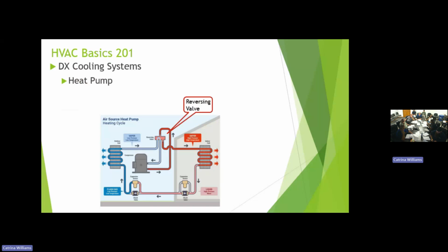So now you get that reversing valve for the heat mode. What used to be the evaporator is now the condenser in your ductwork in your house or whatever it might be. So it rejects the heat into your house instead of outside. The cold air is then rejected outside. That's all that's doing. This reversing valve takes your system and flip-flops it.